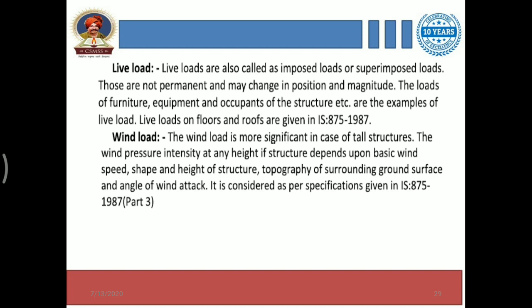Then the third one is wind load. The wind load is more significant in the case of tall structures. Especially wind load is considered when the structural steel structure goes up to 3 or 4 floors or more than that. Okay, in that case only wind loads are considered.